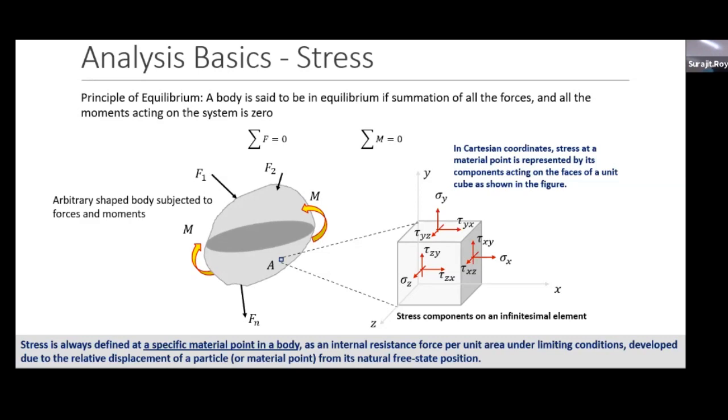As a design engineer, you will see that no design engineer in this world actually uses a factor of safety equal to 1. I have never come across that. It is basically saying that nobody is 100% sure the design is going to work. So people say, okay, I will use a factor of safety of 1.5, 2. The higher the factor of safety, the less confident you are about your design.